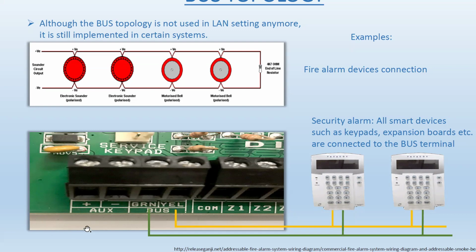For the most part, if it's power, auxiliary, that's the 12-volt power here, that power is supplied to all the active devices, like for example keypads, but I didn't draw those wires here, just to not pollute visually. What other active devices? Motion sensors, glass break detectors, anything that requires power gets power supplied from this plus and minus 12 volts DC.